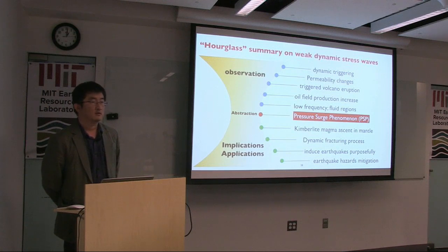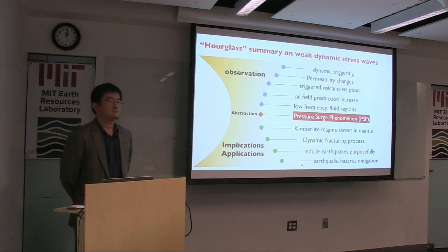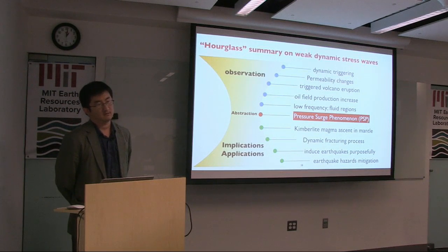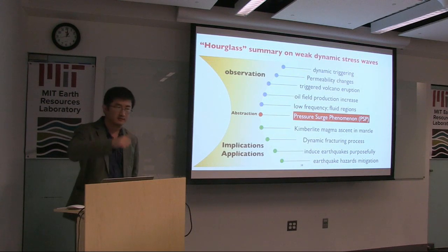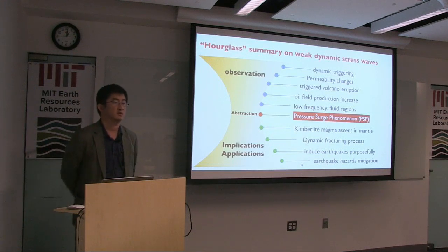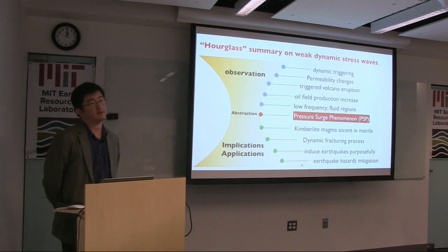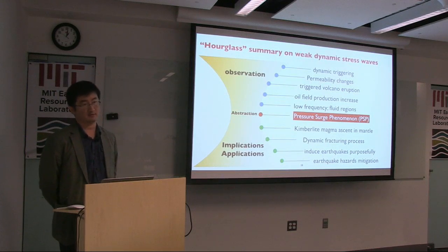Do you know any cases where during hydraulic injections the pump frequency has made any difference in the injection success? I mean, what you're saying is that if you could vary your pump frequency, maybe that's a proxy for pressure. Yes, you maybe could do a good hydraulic fracture treatment at lower pressure if you could change the pump frequency, if you could get an oscillation downhole. I think some companies use pulsed injection, like a series of delta functions, just pulsed injection. So certainly they are thinking about ways to change the pump frequency.